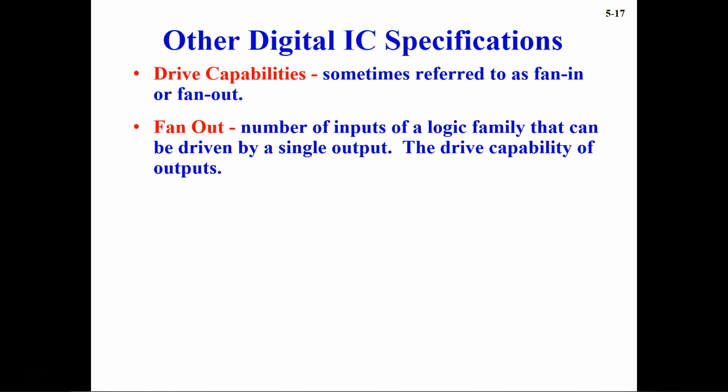So you see how the fan out levels, the number of inputs for a logic family, have increased, and they are different for each of them. For a standard TTL IC it's 10, for low power Schottky TTL it's 20, and for 400 series CMOS it is 50. Now next we have fan in.